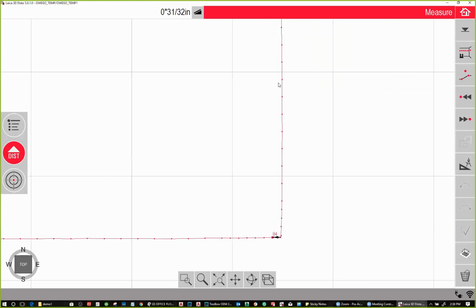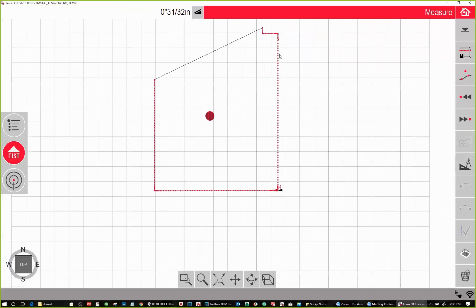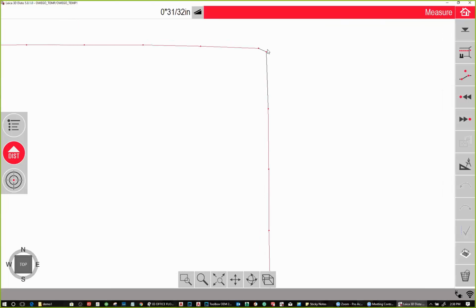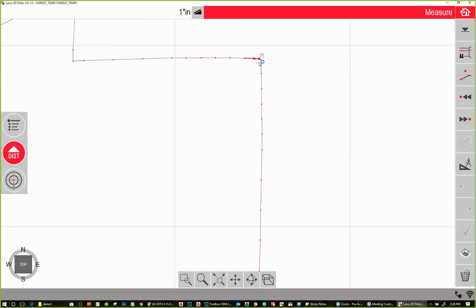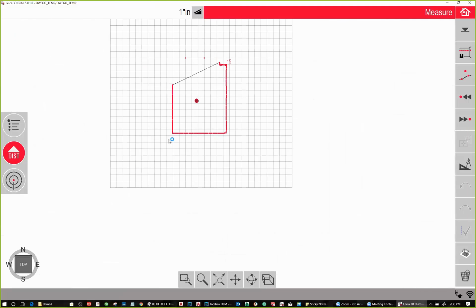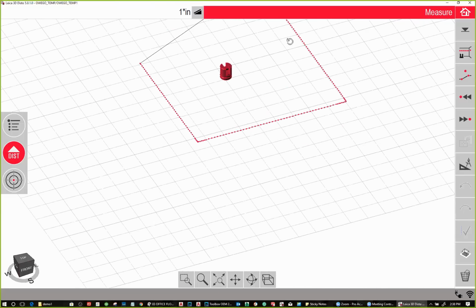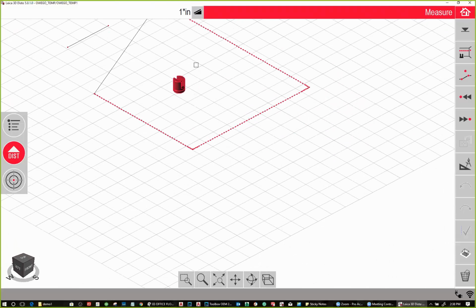And you can actually see here, it picked up the mud. You know, see how it comes in just a little bit. And even over here, it picked up the mud. And like this area where it's a little funky angle, if you just do that fillet command, either in this software or in AutoCAD, it kind of cleans it up. So this scan took me about 20 minutes between setup and takedown. Very quickly able to capture countertops. It's a great, phenomenal tool for that.